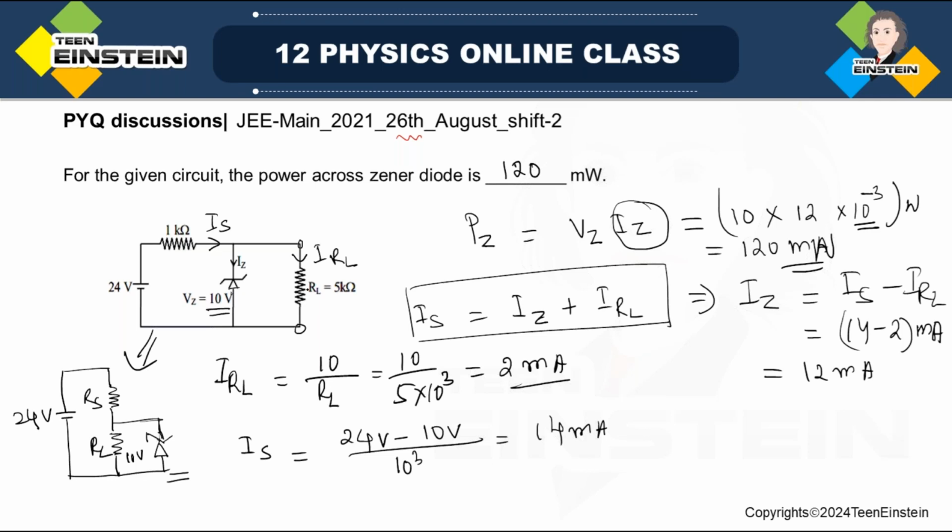All right. Sometimes you might be given IZ. Then you have to find the current, or sometimes the total current passing through this resistor will be given, IZ will be given. Then you have to find the possible or maximum series resistance RS you can use in the circuit. Actually, if you go to the laboratory, you will be given the power of the Zener diode.